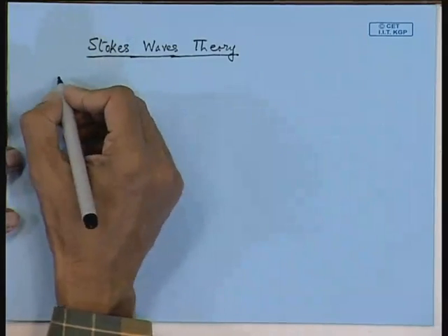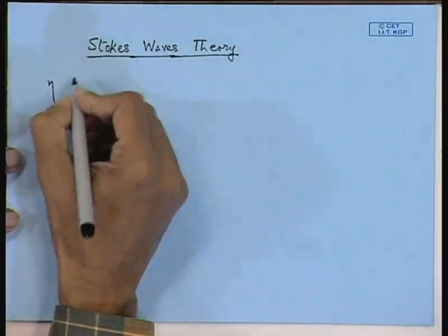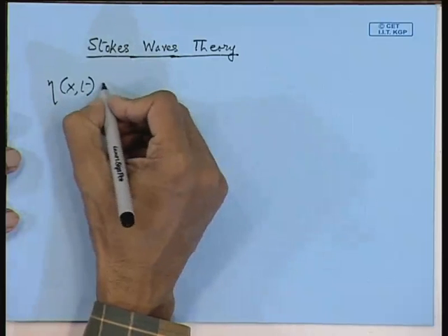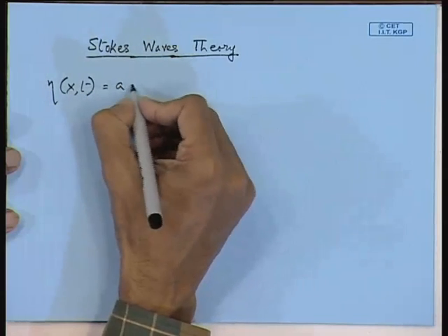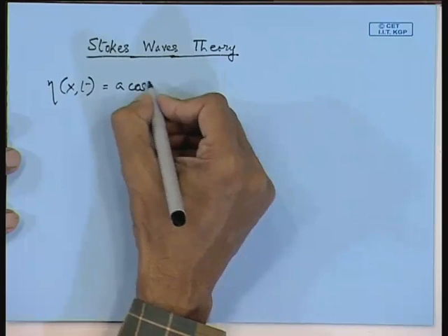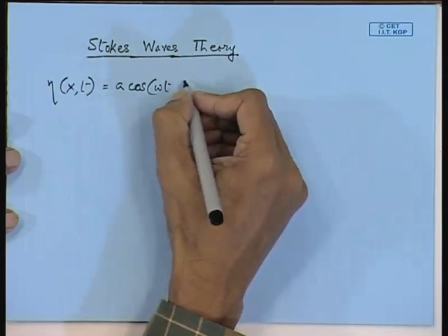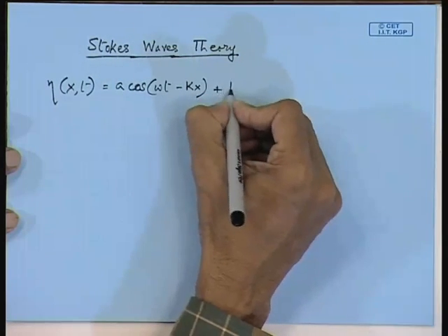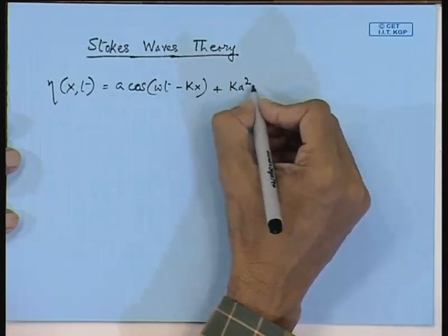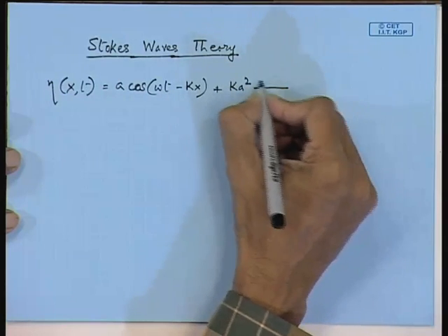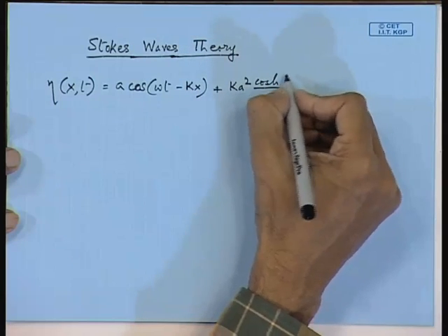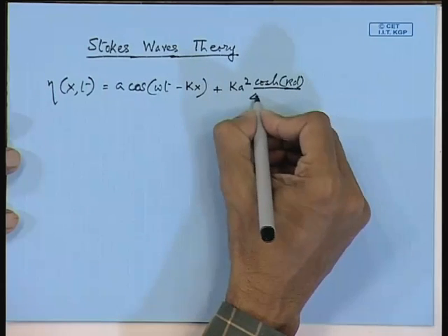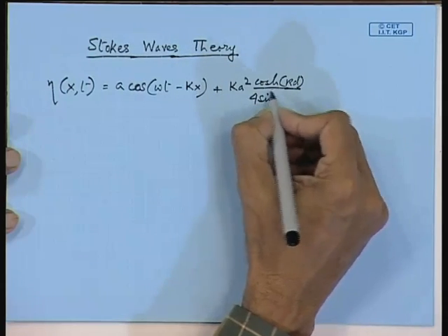Now, in the Stokes wave theory, I told you that you can split up into the first and second and the number of harmonics. So, you will get this kind of equation from the nonlinear Bernoulli's equation or the other non-linearities that are present. Here I am just giving you a glimpse of what you have to do. So, this is coming like this. Now, the problem that will come is in shallow water. So, 4, this is sine hyperbolic cube.